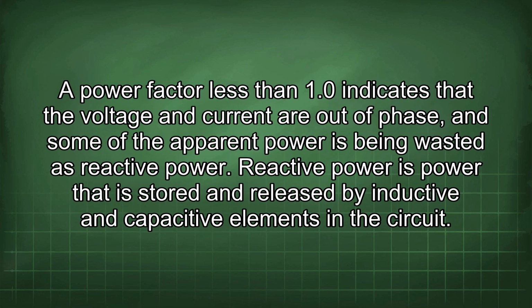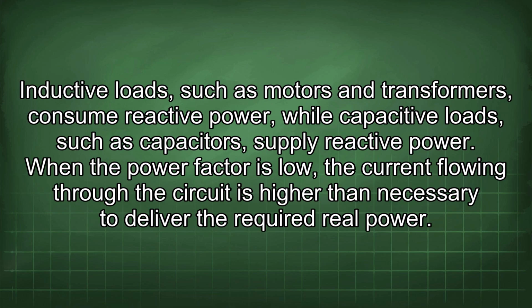A power factor less than 1.0 indicates that the voltage and current are out of phase, and some of the apparent power is being wasted as reactive power. Reactive power is power that is stored and released by inductive and capacitive elements in the circuit. Inductive loads, such as motors and transformers, consume reactive power, while capacitive loads, such as capacitors, supply reactive power.